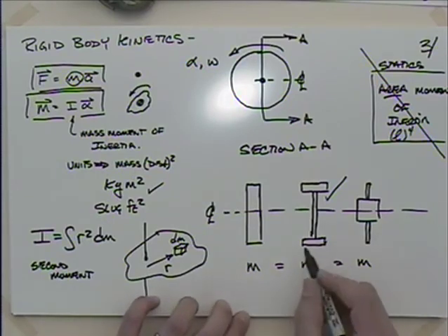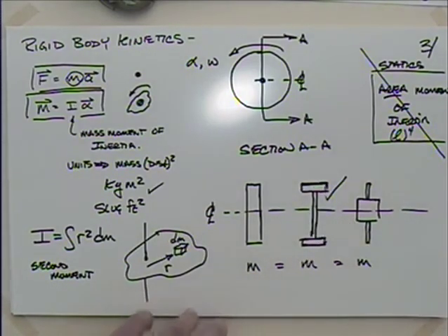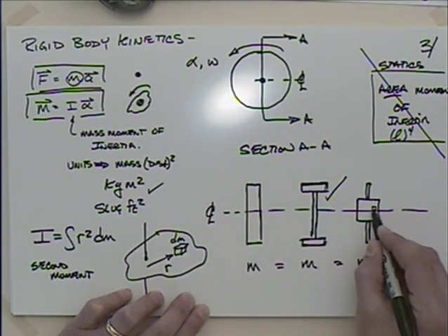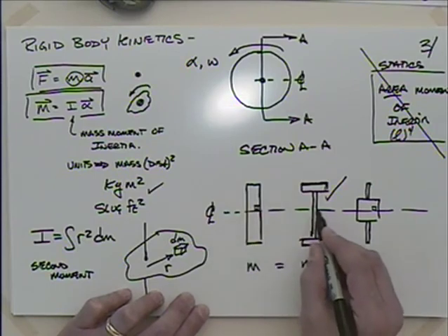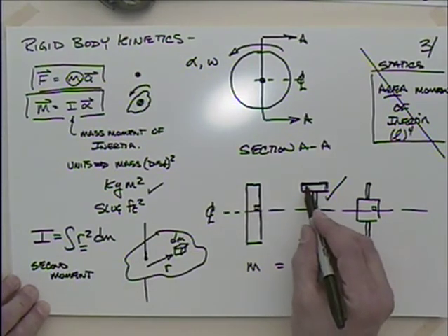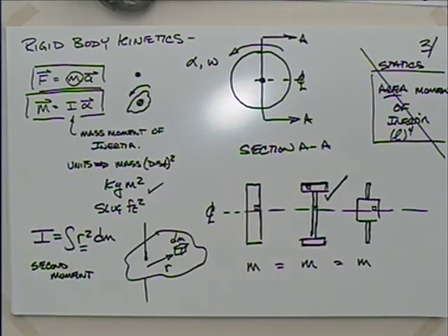So this is why oftentimes our flywheels have a very heavy rim and then a lighter center, because that way we can put the mass further distance. For instance, this little chunk of mass here, or this little chunk of mass there, or that little chunk of mass there doesn't do much good when you're thinking about squaring r, right? So that's why we try and concentrate the mass further distance out. So this is going to have a much higher I, which is good if you're not wanting to slow down. It might be bad if you're having to accelerate it. Questions with that?